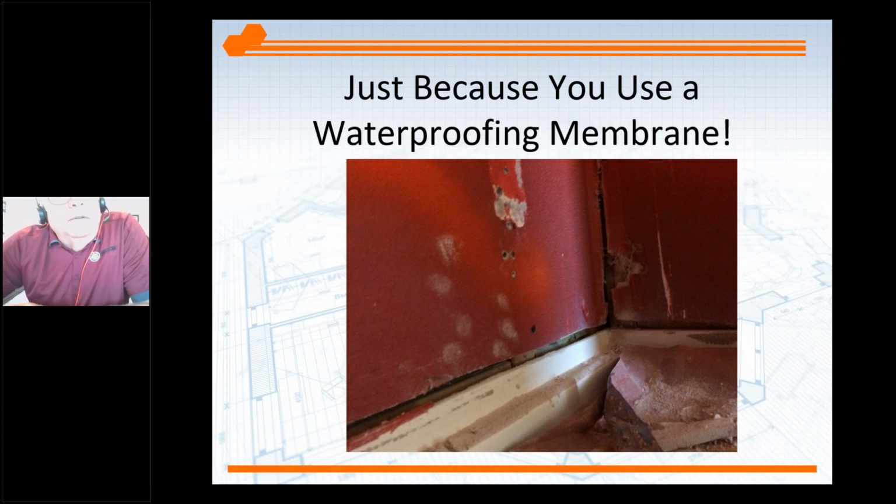Generally, that's going to be your backer board installers. And with the tile installation, they should be using a fiberglass mesh tape and cement adhesive. Don't let them use the paper tape and their gypsum adhesive. These are not meant for wet areas. And water moisture does get behind these, even if it is a porcelain tile. So be very aware of that.